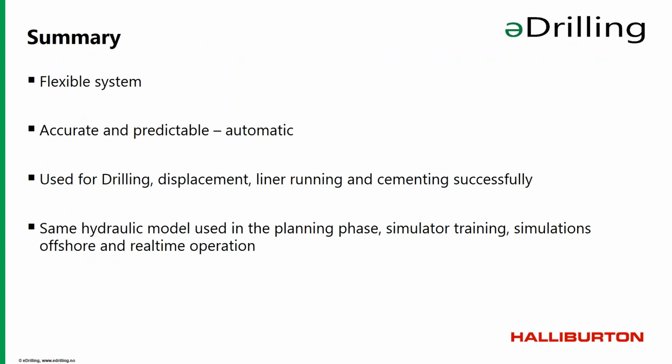So all in all, using MPD gives you a flexible system. You can easily and very quickly either increase or decrease the bottom hole pressure. In a conventional system, you would have to weigh up, which would take a long time. You can use the system for dynamic FITs and dynamic pore pressure tests. The system, as it's automatic, is also accurate and predictable.